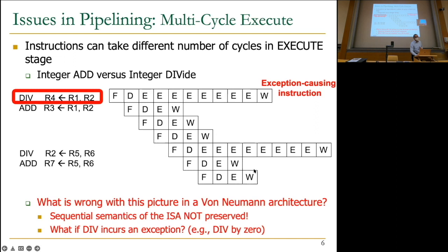Whenever you inspect the contents of the register file, which is exposed to you because you can actually do that, you should not see updates from any later instruction in program order that comes after divide. And you should also expect that every instruction before the divide must have finished and updated the register file in memory. That's the expectation, so that you're able to debug this program, right? Otherwise, it's very difficult to debug this program.